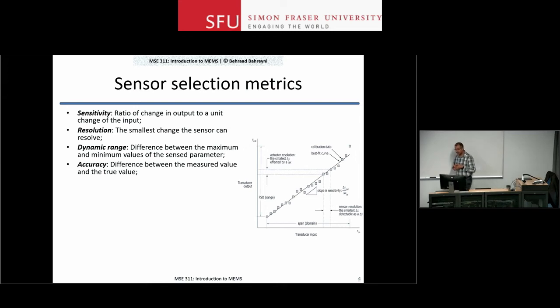Accuracy is about how true the value that you read at the output of the sensor is. In other words, how close is the output of that sensor to the true value? So if I measure, let's say, the temperature in this room with an ideal sensor that is well calibrated and has no error in it, and it reads some value, and I read it with my cheap sensor here, how close is that value to the response from this ideal sensor?